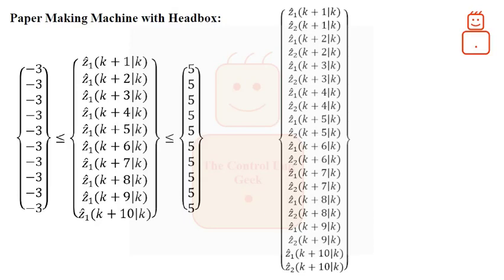This is because we have a prediction horizon of 10 and, at the same time, we have 2 controlled outputs. Thus, each output will have 10 future predictions, and this will make our final vector have a length of 20 by 1. Keep in mind, we have taken HW to be 1. If we considered HW to start from 0, then each control output would have 11 future predictions, and this would make our final vector have 22 items.